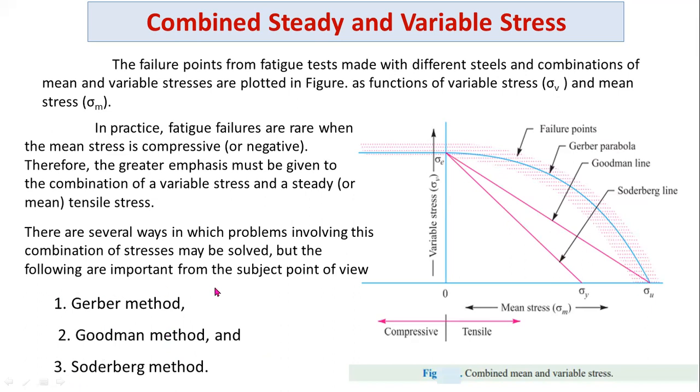Of these three methods, the Gerber method is not used in present days because some failures are there. Goodman's method and the modified Goodman's method are widely used for steady and variable loads. In this session, I'm going to explain these three topics, and I will also show you how to derive an expression for the Goodman and Soderberg equations.